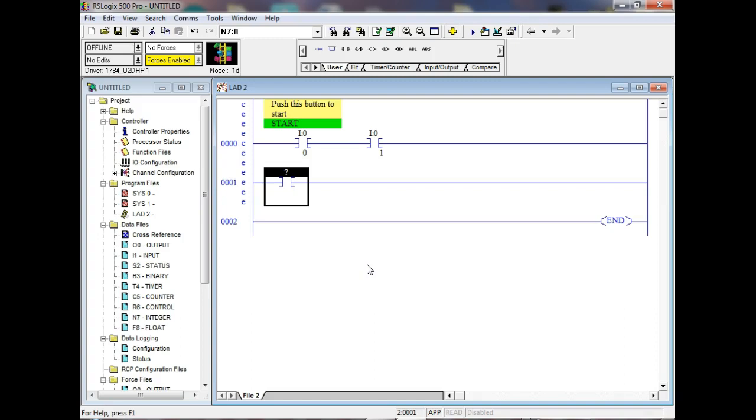Now over here on this 500, since this is a modular PLC, then your address 0 is taken up by your CPU. It's slot 0. So if I wanted to address this input module right here, I would have to say 1. I would say I:1. If I wanted to output any of the 16 outputs on this guy, I would say I, right, :2. If there was a module here, this would be I:3, and it would be all the devices that are contained within that module. That make sense?